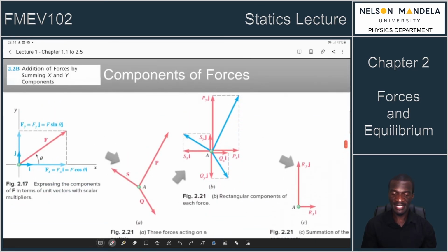Now, these forces can be the resultant. You can actually add forces by summing their components. This is the best and most recommended method of finding the resultant. Decompose your force or your forces into x and y, and if given, j directions. For now, it's just 2 dimensions, so we'll talk x and y. So decompose your forces into the x and the y direction. Then when you're done with that, just add all the x components, just add all the y components to find the resultant.